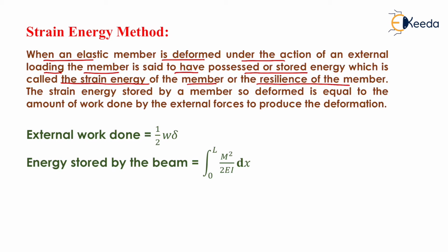It means that when an elastic member is deformed under the action of an external load, the member is said to store some energy, which is known as the strain energy of the member, and it is also known as the resilience of the member. Now the strain energy stored by a member so deformed is equal to the amount of work done by the external forces to produce the deformation. It means that the total internal strain energy of the body will be equal to the total amount of work done by the external force to produce the deformation.